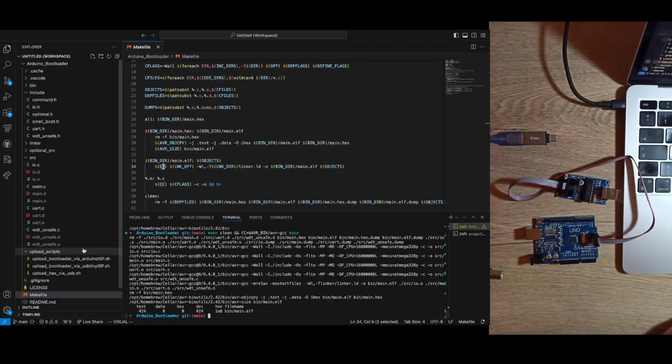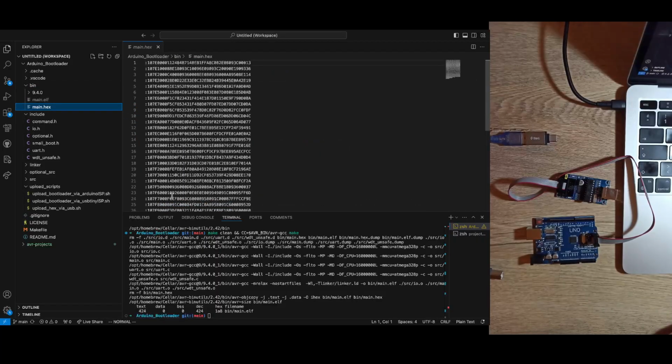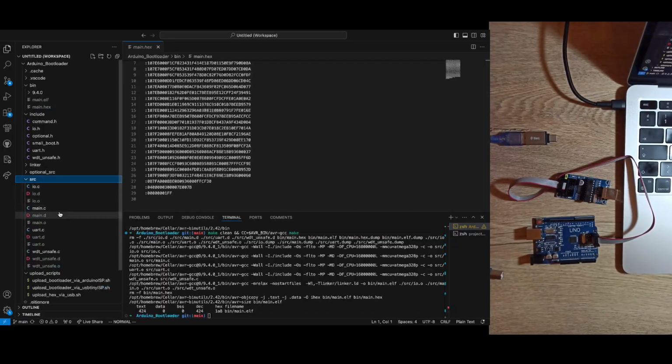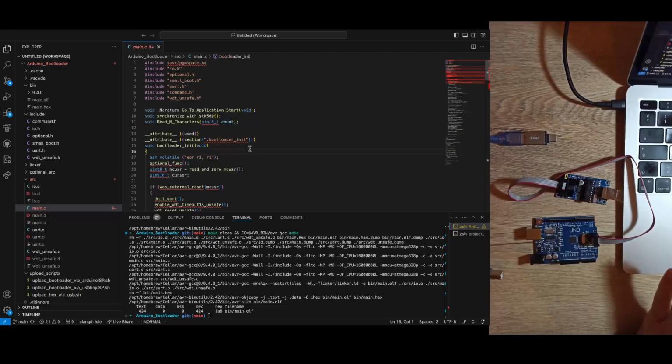We've got a binary hex here, main.hex, of size 424 bytes, which fits inside the half kilobyte restriction in the boot flash section. So let's look at the code again. Let's look at main.c. I'm going to talk about how my indexer works. The indexer is not a must, but with VS Code, with how I program, I use the clangd C indexer, and I find it very convenient.